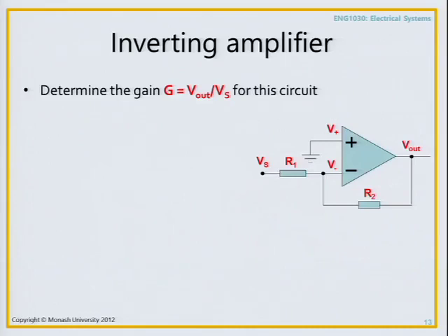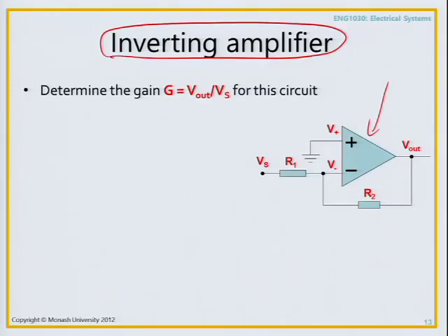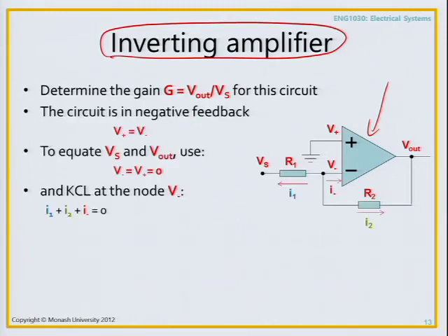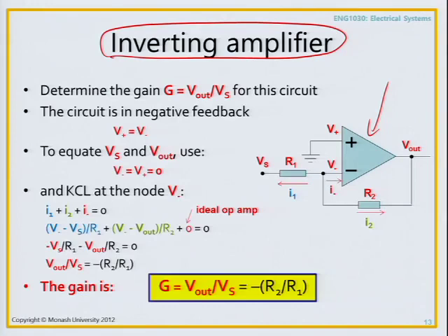Okay, so that in fact was the exact circuit that we had, and that is called an inverting amplifier. Here's all the working, redone. The reason is because, as I said, the gain of V out over Vs overall is equal to minus R2 over R1.